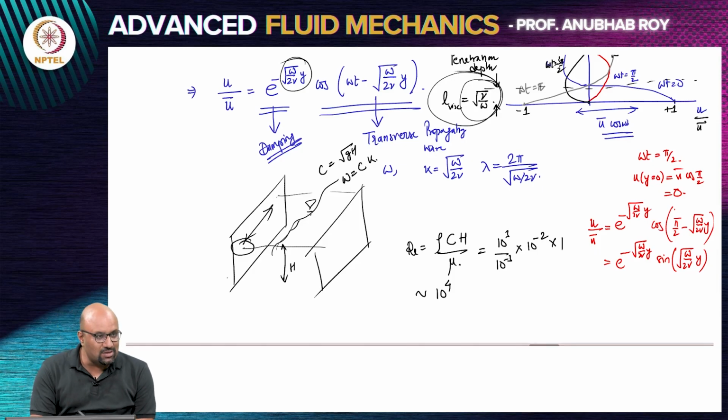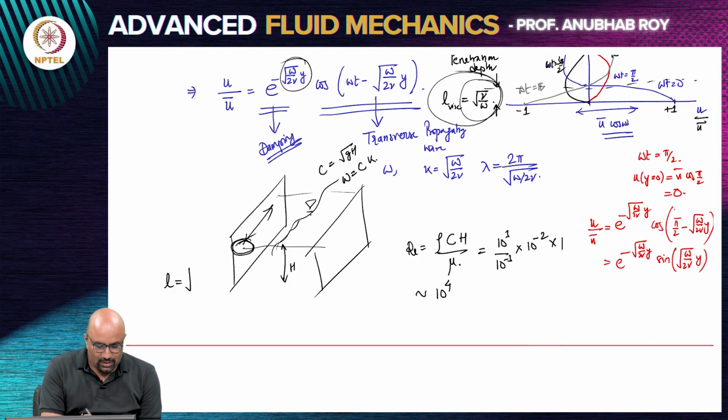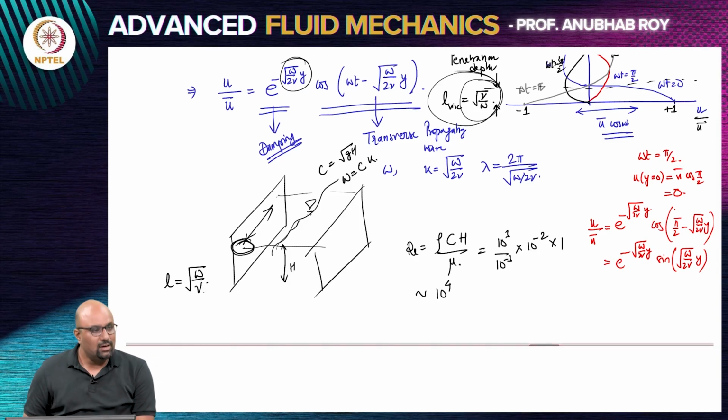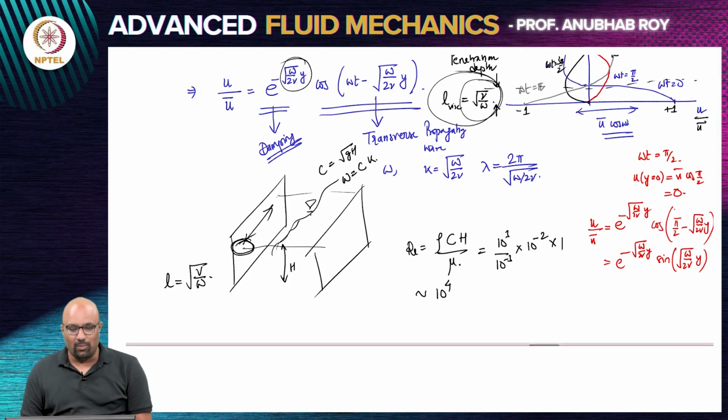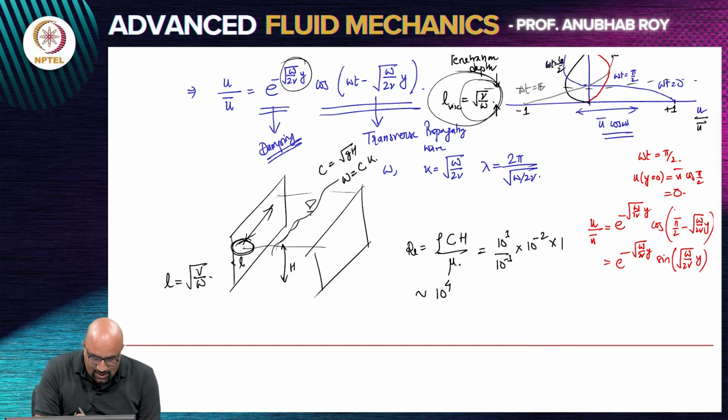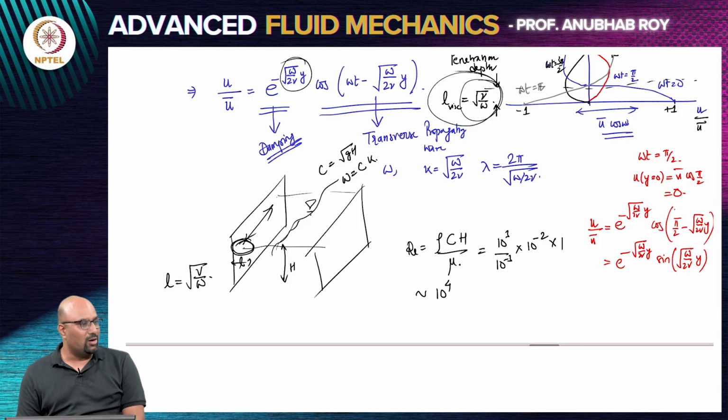And to quantify the dissipative effects, basically you will say that there is a length scale, which is the penetration depth, that is going to scale as square root of nu by omega. So, over that distance there will be damping that will act in the problem. Omega by nu has inverse length square dimension. So, nu by omega basically gives you the length over which damping is going to happen in your problem.